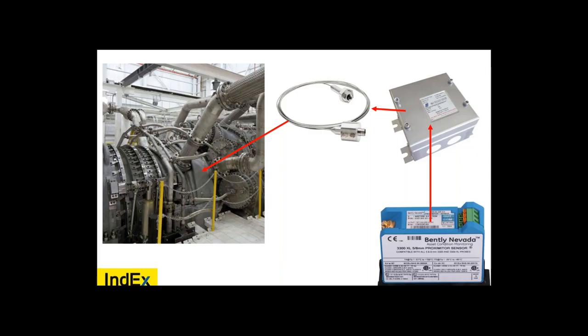Is there a protection technique that does not have to have EX components inside? EX p and d are 2 of 3 that do not need to have EX certified equipment inside. We spoke about the other one today. Will this be available on YouTube?